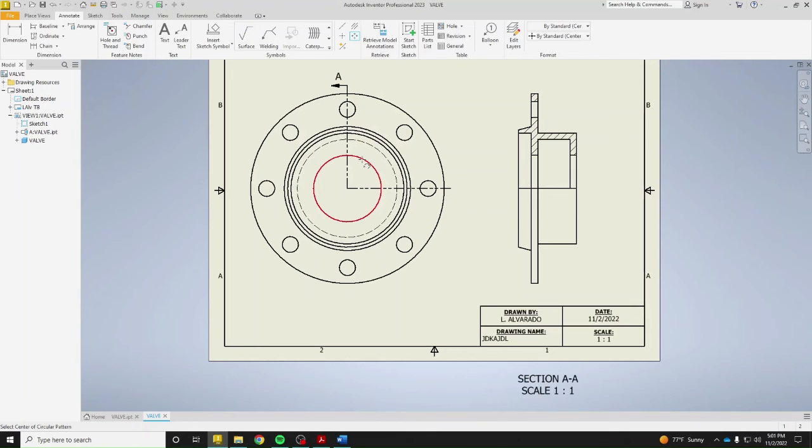So I can click on the circle, or I can click on this center point. I'm going to click on the circle, and then I'm just going to go ahead and click on each individual circle as I make my way around, clicking on that final one, the one that I started with, and then I'll right click create, and here is my centered pattern.